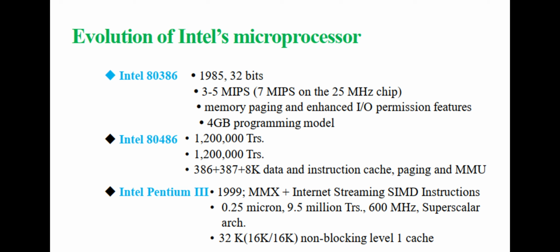Intel Pentium III, 1999, MMX and Internet Streaming SIMD instructions, 0.25 micron, 9.5 million transistors, 600 MHz, superscalar architecture, 32K, 16K/16K, non-blocking level 1 cache.